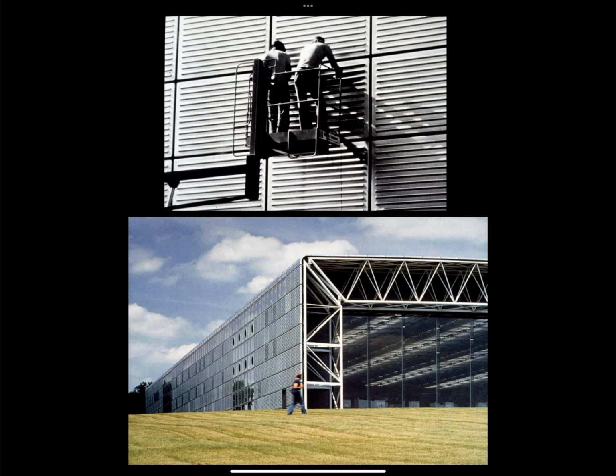The silver that you see, the building is silver, the finish is silver, and this is a painted finish applied to the aluminum. It's not the aluminum itself. So it's a factory applied paint finish, very high specification. And this is because, as I mentioned before, when aluminum oxidizes, it's a dirty gray color that is not very appealing.